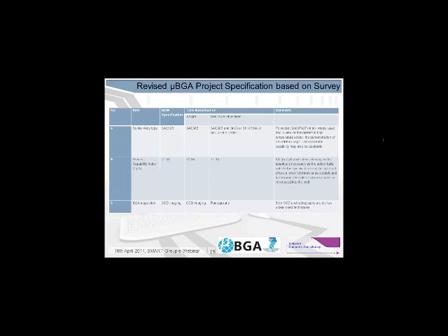The core solder type of SAC 305 has remained consistent, though we also want to look at tin 63 for consumers still using lead-containing solder. We'll also be looking at some higher temperature solders, as respondents from the automotive, aerospace, and chemical manufacturing industries stated that they required solders with higher melting temperatures for some of their